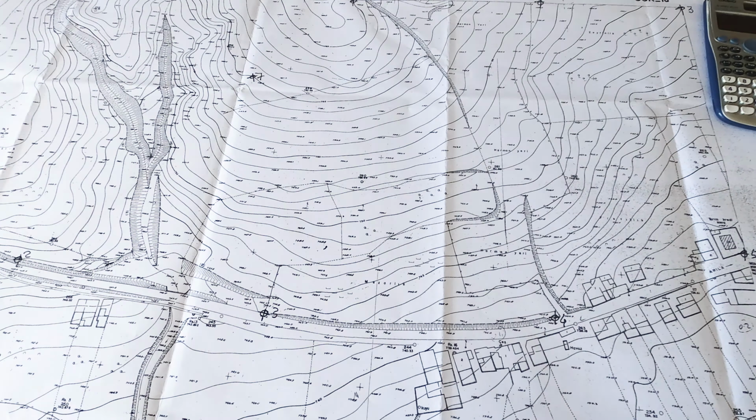So for the given map, we have the contour lines in here. According to these contour lines, for the thick lines in here, it's 755. Going to the other one, it's 750. That means each contour line here represents 1 meter difference in height. According to this, and to the scale given for the map, 1 to 1000, that means 1 millimeter on the map equals 1 meter on the site. Now the difference here is 1 meter.